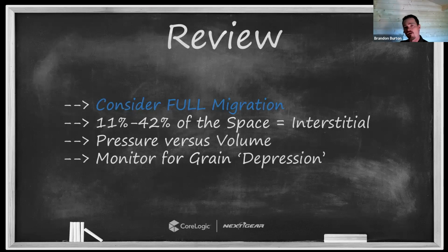My drying chamber is also the cavity in the wall behind me, potentially, if water has made it into that space. That needs to be part of my drying chamber. And so another good way to think about it is, where is the edge of your drying chamber? Is the edge of your drying chamber this wall surface, or is the edge of your drying chamber the other end of that assembly, right? The back surface of the next room, right? Is that the edge of my chamber? And the edge of your chamber needs to include the totality of that migration, right?